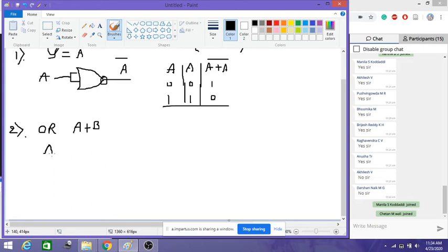So then it's very simple here. A plus B, you apply the double inversion and we'll get the A plus B itself. It means you take out this bar, I'll get A plus B. Now if you look into this first bar, it is exactly in the NOR equation. Now if you complement that output with one more NOR gate, we will get the OR gate.